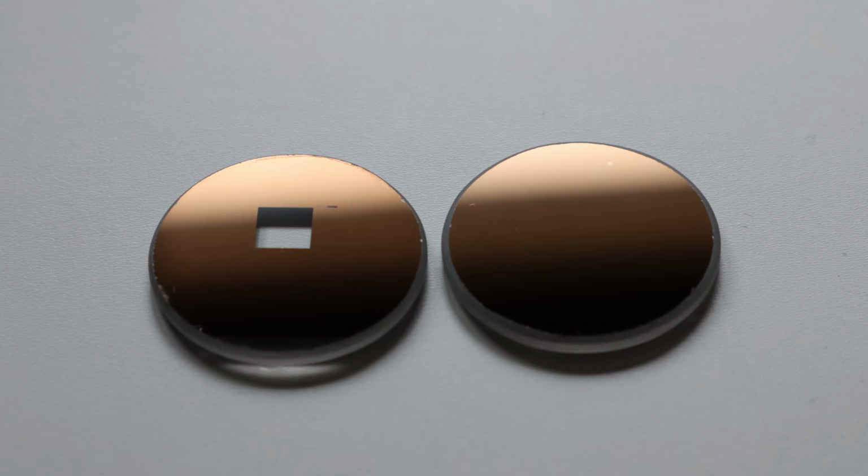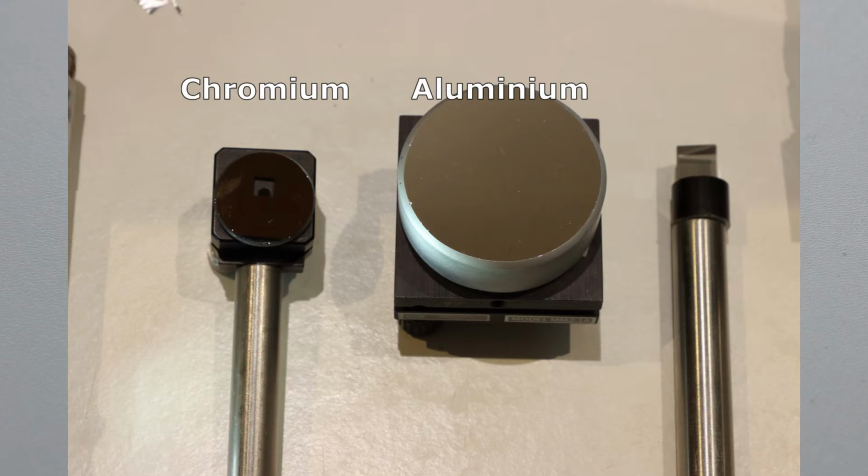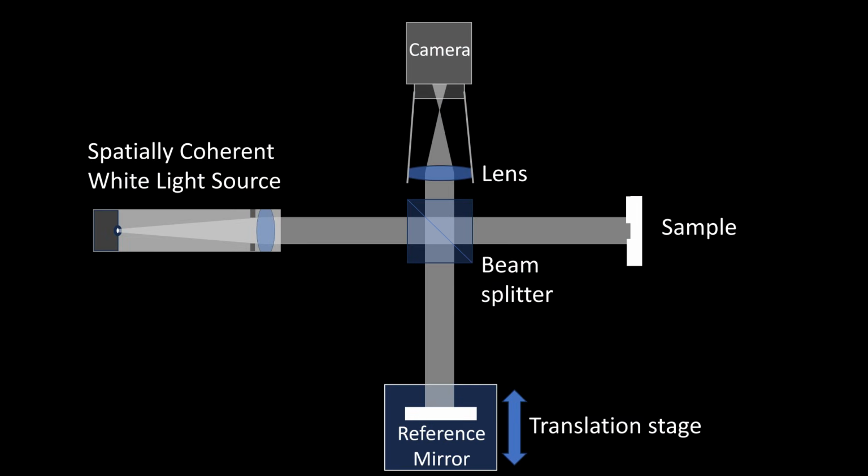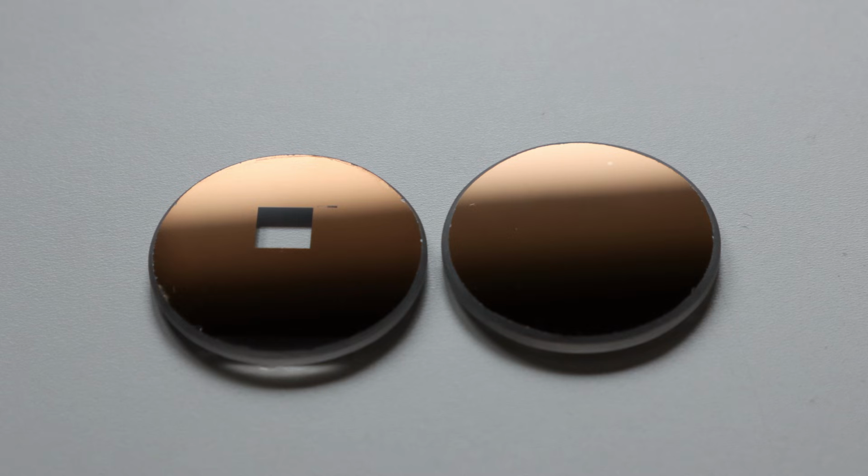As you can see, the chromium layer looks a bit dull, brownish, and it's certainly not a very efficient reflector like an aluminum surface. Now, why use these two interfaces for the test? Well, interferometry measurements work best if the two beams that we combine have comparable intensity. And so, because the sample with these nice test patterns was cut out of an old photolithography mask, I had to use a reference surface with a comparable reflectivity.